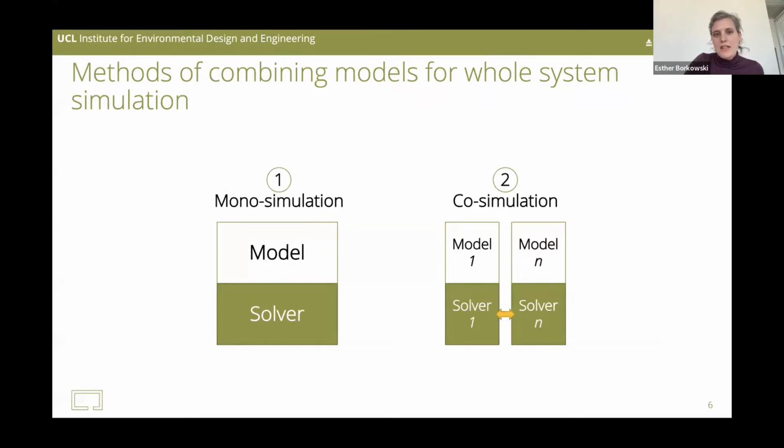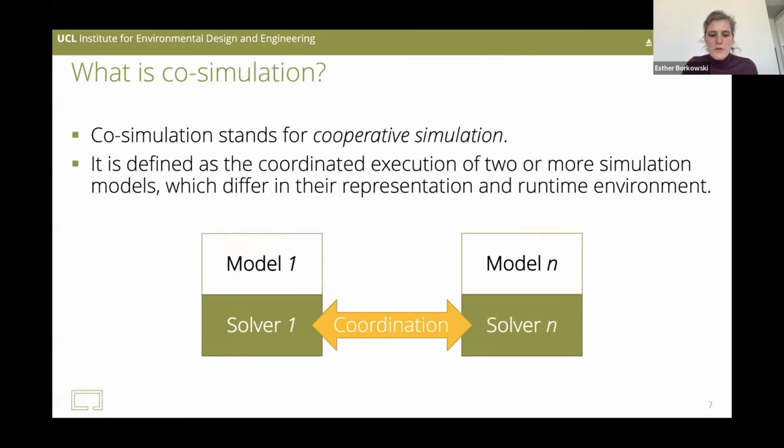Co-simulation, on the other hand, refers to the joint simulation of separate models developed in different tools. The models are run in individual simulators, and they can work together. While the tools communicate with each other at specific times and synchronize outputs such as variables or status information, each tool independently solves one part of the coupled problem between these communication points.